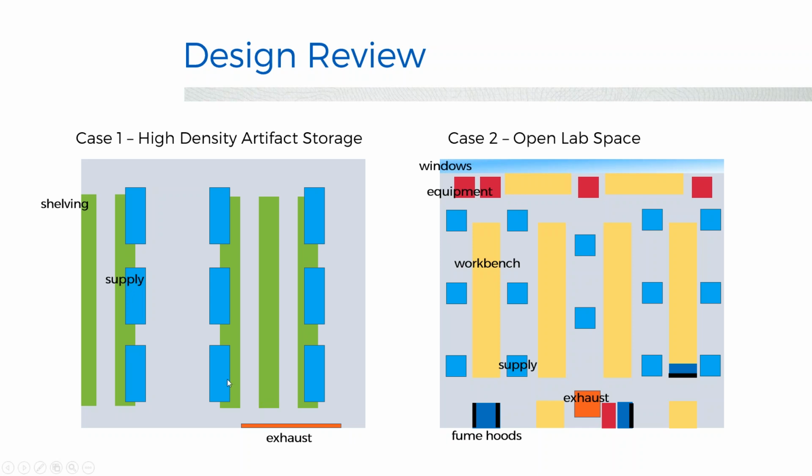So just from looking at this design, we can see that just from a knowledge of how air behaves, it tends to take the path of least resistance. So we want this air to go down all the way to the floor level and flush out all these aisles. In reality, it's likely going to either go across the tops of the shelves or mainly stick to these wider aisles where it can flush down easier. Just looking at this as well, we're also probably fairly likely to get short circuiting here and into the exhaust.